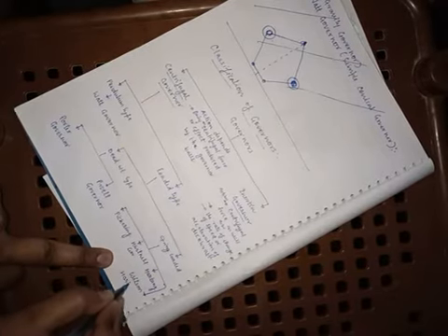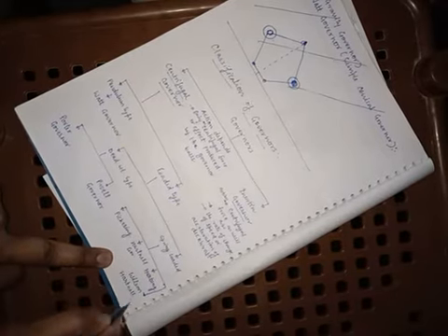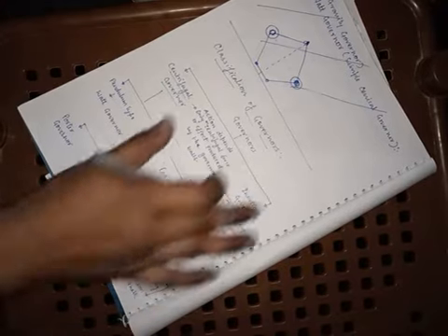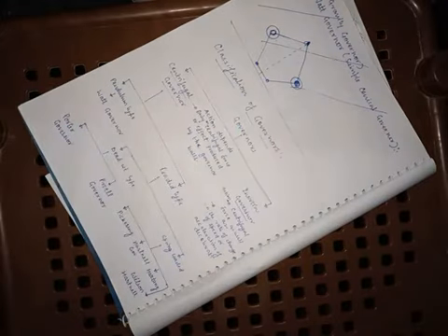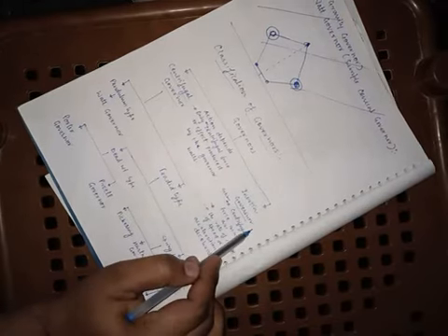So these governors are classified into two parts: centrifugal governors and inertia governors. Centrifugal governors are those whose action depends only on the centrifugal force or effect produced by the governor balls. But in case of the inertia governor, its action depends not only on the centrifugal force set up by the balls, but also on the rate of change of speed, or acceleration and deceleration of the balls.